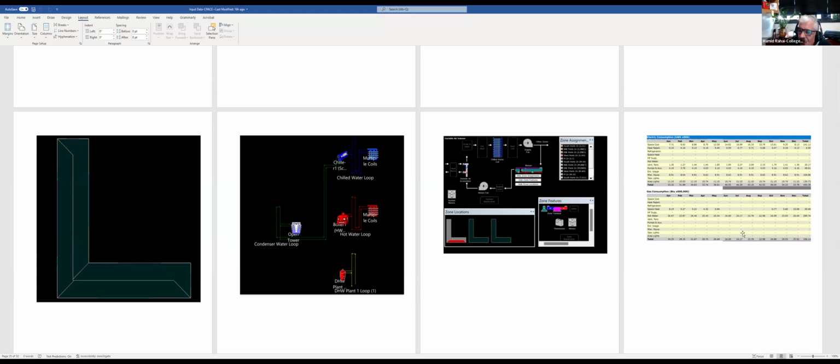That will give you energy use intensity. And then you can compare that design with the baseline design or your goal to see if you meet that goal. If not, then you go back through these windows and choose a different kind of system, different orientations, and so on. So it gives you a chance to play around with these parameters to reduce energy consumption.